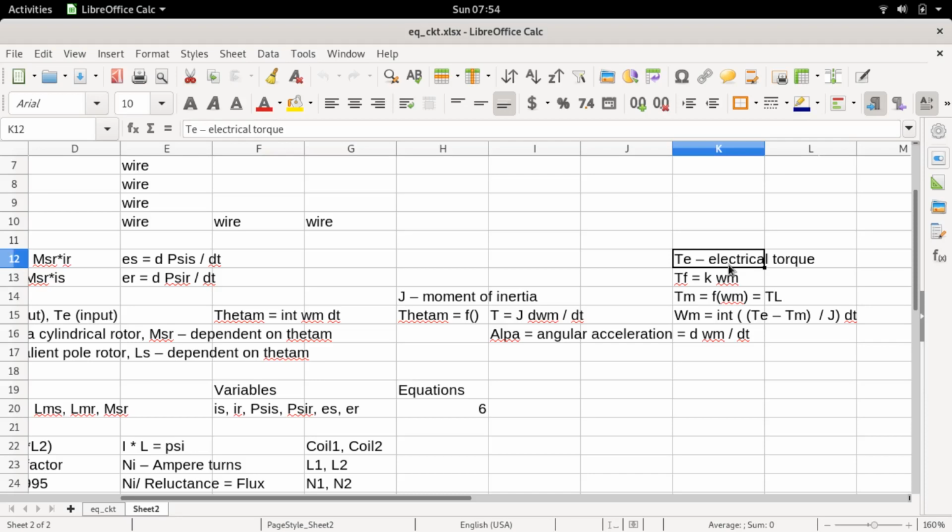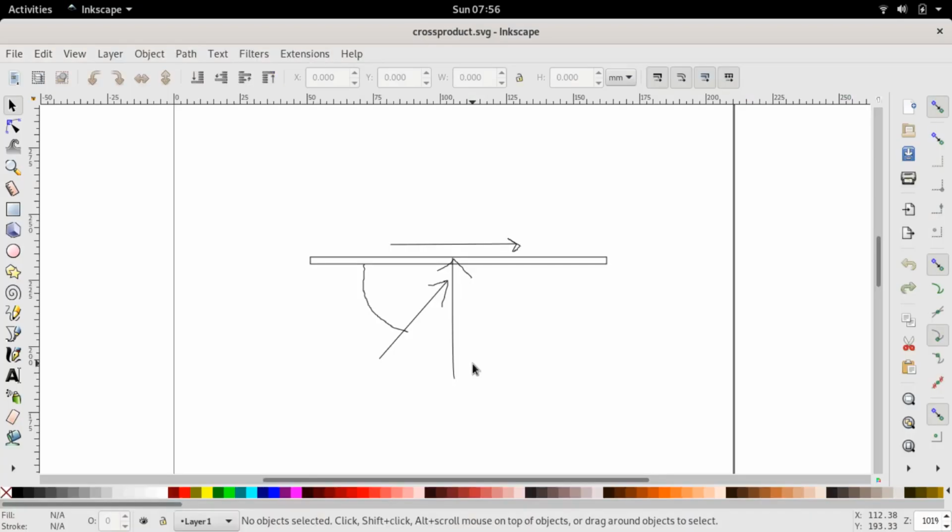And using this, we can determine the nature of mechanical force in this case as well as for any case. So for example, this is a general case. If we consider that this is the direction of the magnetic field and this is the direction of the current, then quite obviously, the mechanical force experienced by this current carrying conductor is going to make it jump out of the page or out of the screen. And if on the other hand we were to reverse any of them, you will see that this mechanical force would cause it to push back within the screen or behind the screen, right?